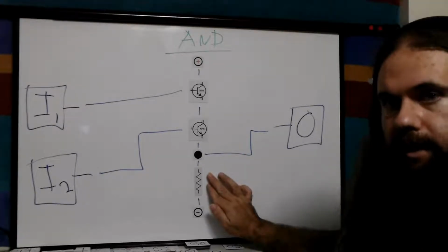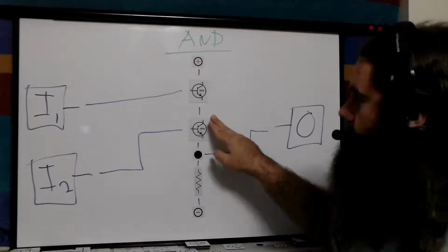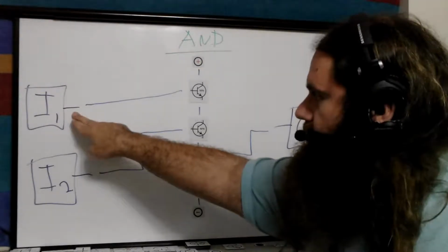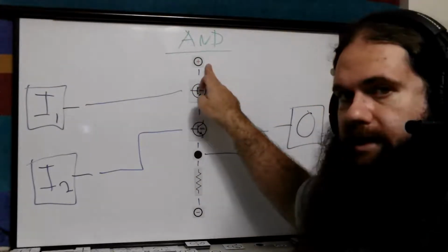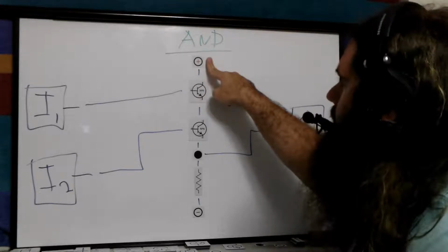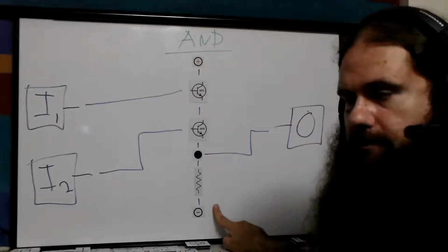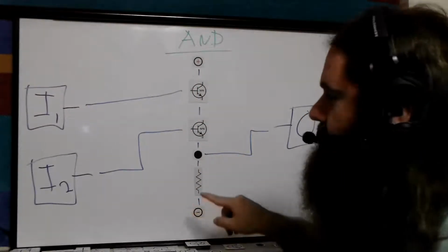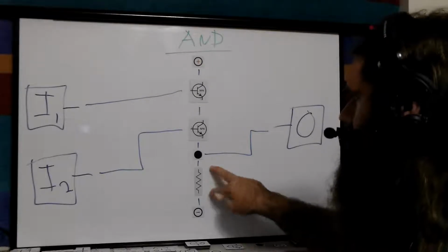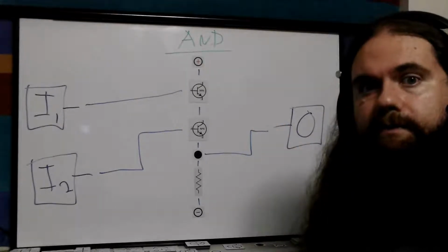But not yet. We're not conducting yet. So right now we have 0 here and about 0.2 here or whatever. So this is still pretty low. And we've got high here, so it's still forward biased. So now it leaks through again, it's conducting, and now we got the power, and now we have 5 volts to maybe 4.8 to 4.6, down to 0. Once we have forward biased these junctions, the electric field has established itself, and now it's conducting. So now the voltage here is about 4.6, which is high enough to act as a 1.